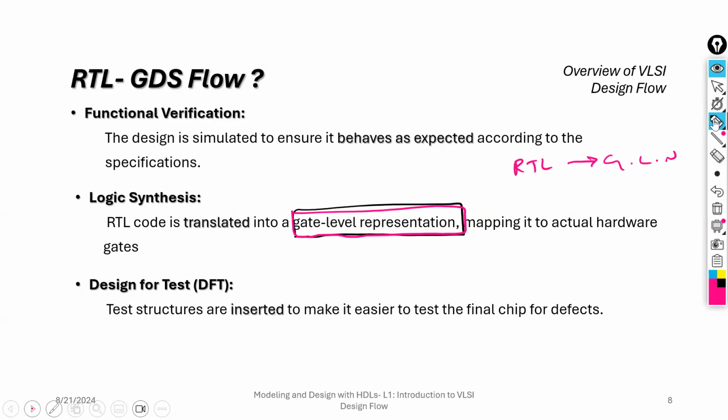We did not worry about how we can test the IC after the fabrication. This provision will help us test the IC very easily. So that is what design for testing is. During the design phase, we perform this kind of thing. Once you create the logic synthesis, after that we insert some scan cells within that particular gate level netlist, and we'll perform the logic synthesis for that again.